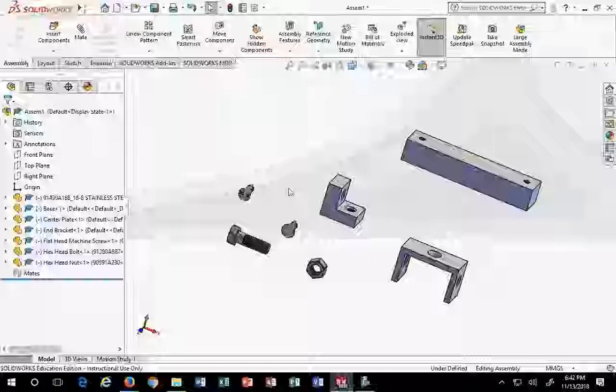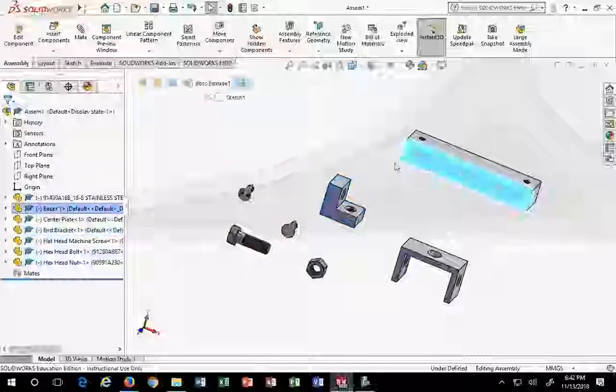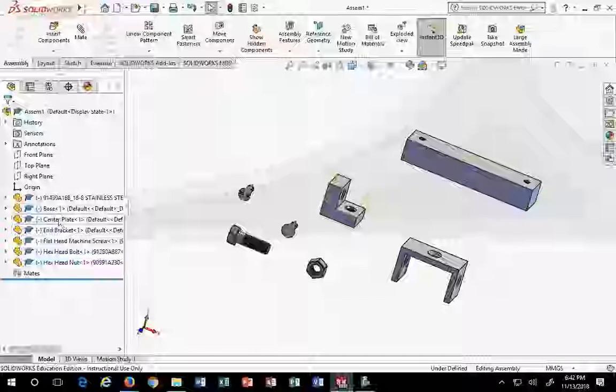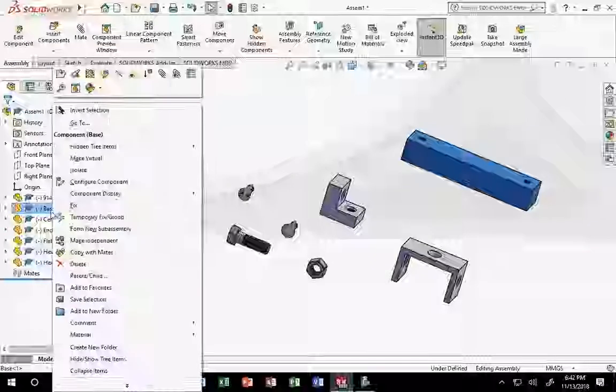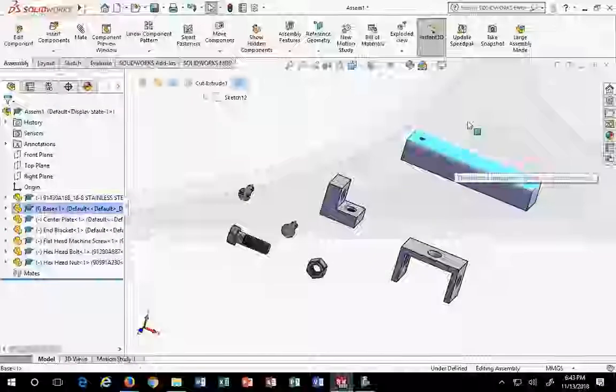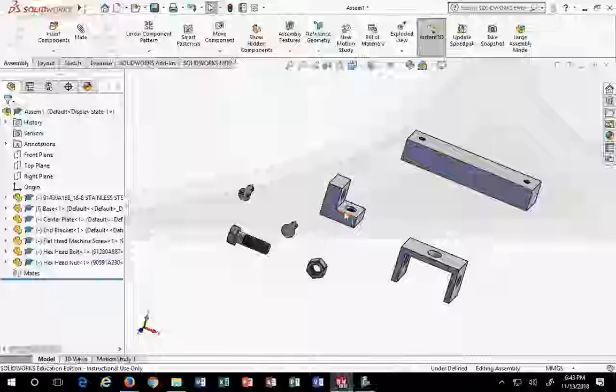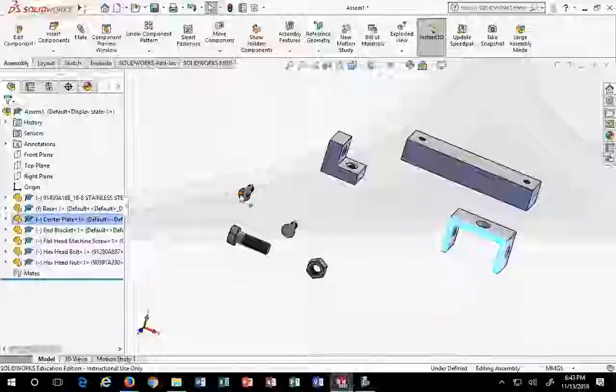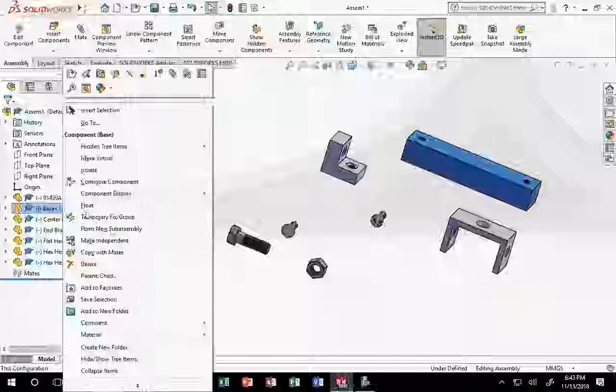If there's an item you must lock down that you don't want to go anywhere, you fix it. Okay? Let's say the part I want to lock down is this one. I'm just being random, all right, guys? I'm just going to pick this, right mouse button. I want to fix that. This will not move. All of the rest will move. And then the nice part is it'll move to that without any issue. Then you can float it.